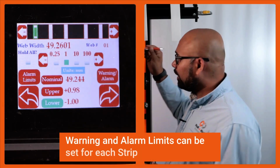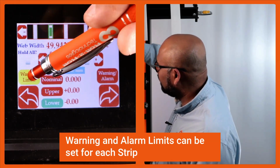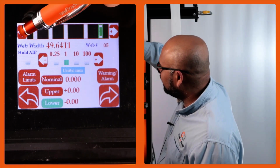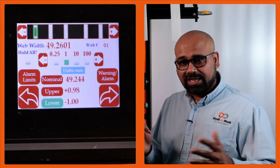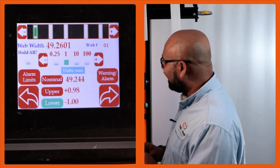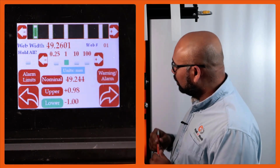And you can do that for every single web. You can set the upper limit, lower limit, alarm and warning limits. Right now for web 2, it's not set up. Web 3, you can see what is set up there. None of these are set up there. But that's the way for us to set this up for the alarm and warning, so that when the width changes, you have the ability to provide a digital output to a stack light or something like that. So that is essentially how to set the multiple width measurement, these warnings and alarms.